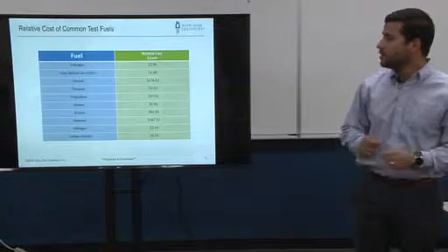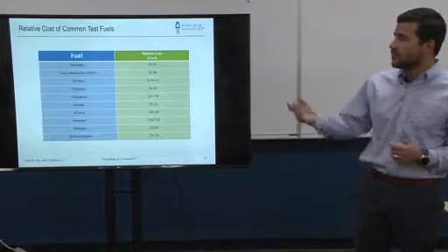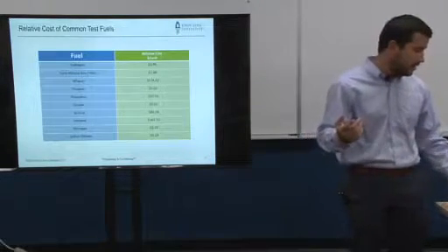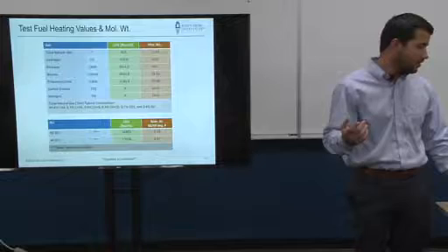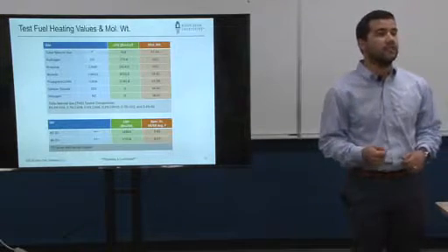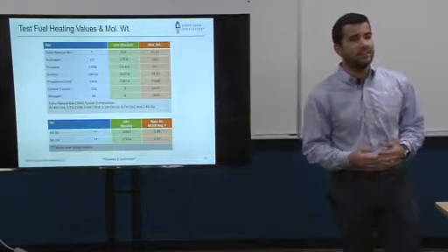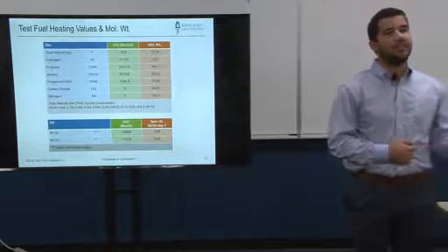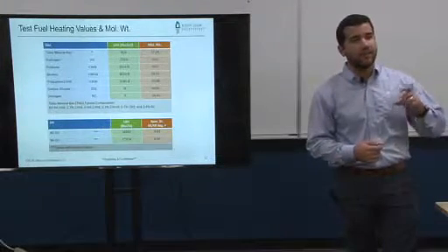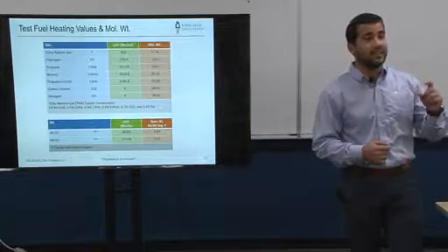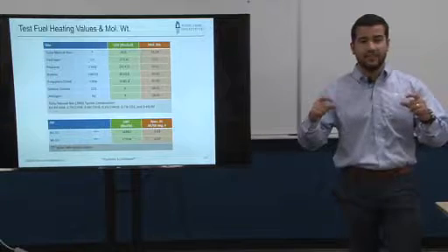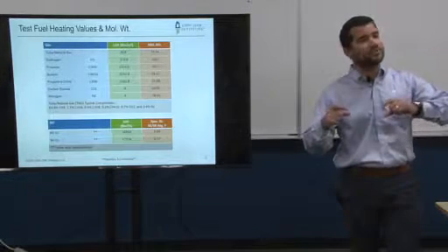But there are other things that you want to look at, in the sense of, look at hydrogen, for example. It's only 3 times the cost of natural gas. But if we take a second and look at the LHV, the heating value of hydrogen, it's actually 1/3 of natural gas. So by the time you do the math, if you figure out the amount of flow that you need to get the same heat release of hydrogen compared to natural gas, then hydrogen becomes about 10 times more